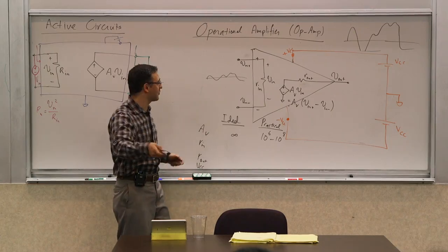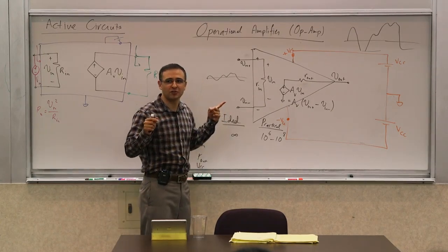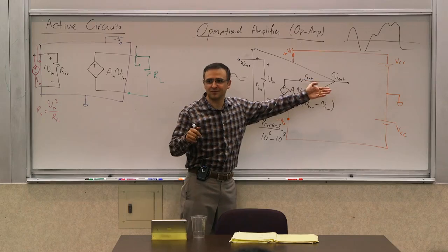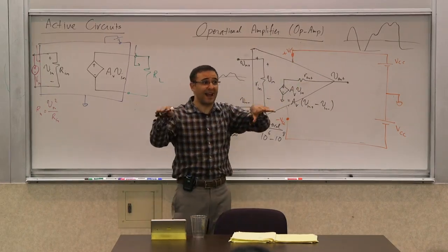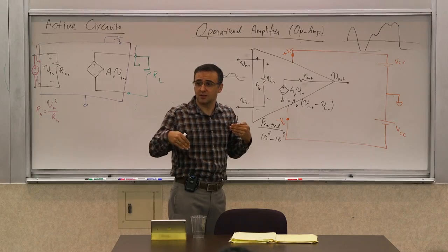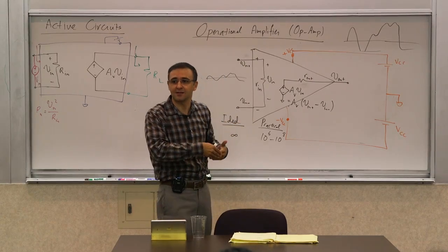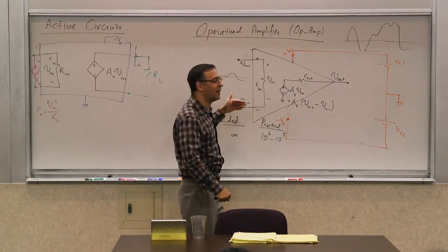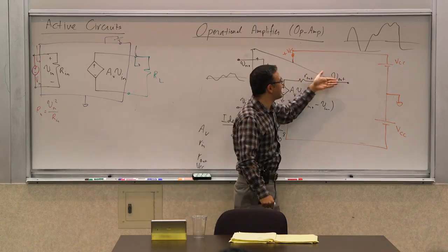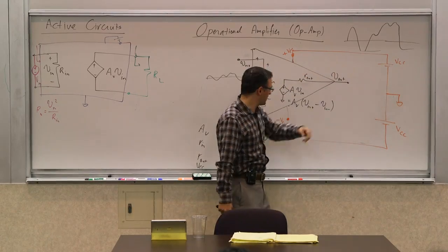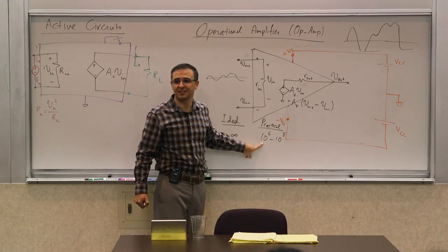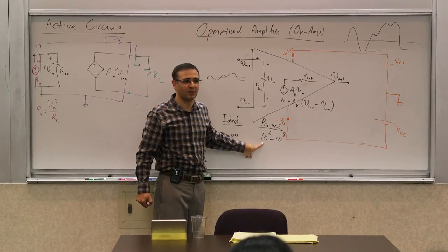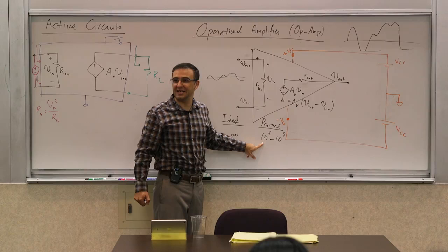Yes, stack them. I mean, stack is probably not the right terminology. Cascade them or put them in series. Stack means put them on top of each other. That terminology is also used for something else, so we want to save it for that. You want to cascade them or put them in series. Because once you put two of them back to back, what will your gain be if one of them is 10 to the 6? 10 to the 12, right? Because they multiply.